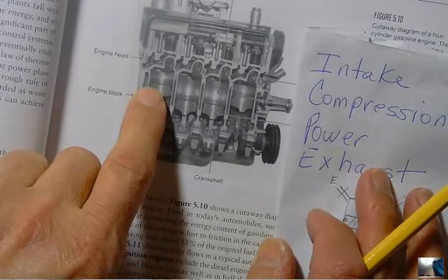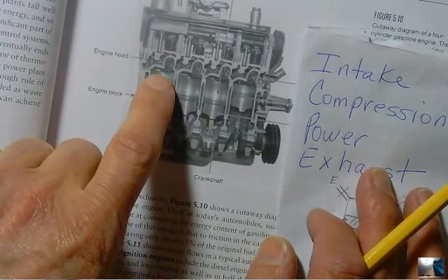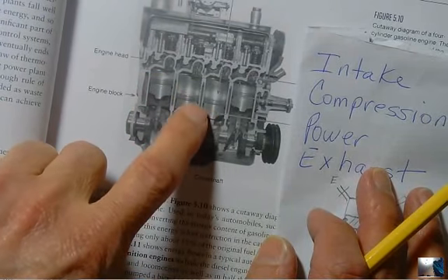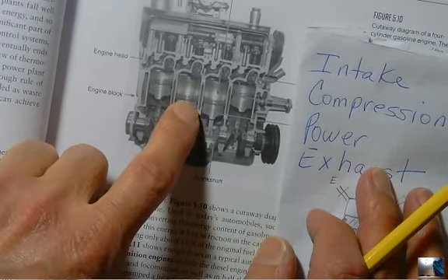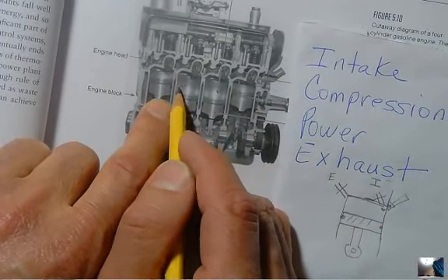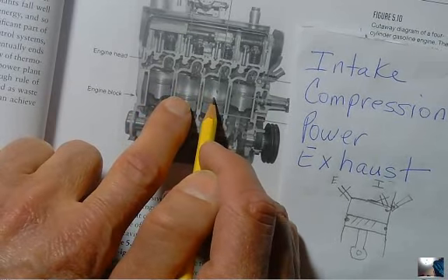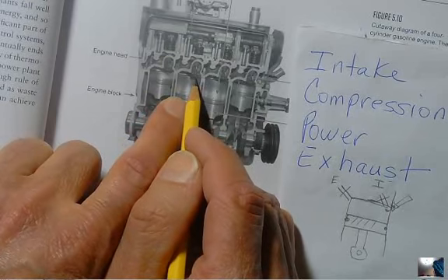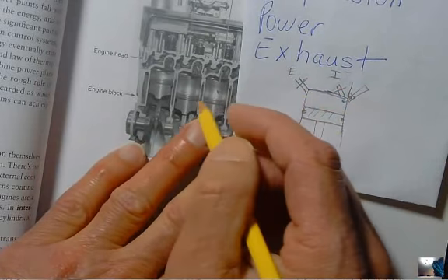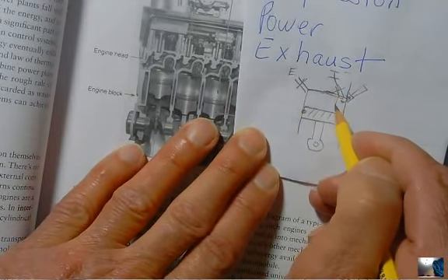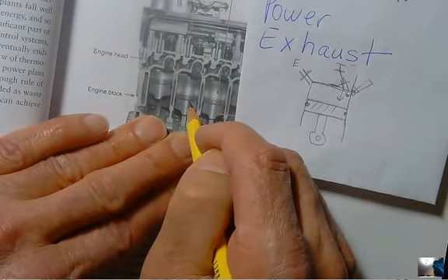If this cylinder number 1 over here is kind of up towards the top, let me start out with these 2 down ones. These 2 down here are just finishing up the intake stroke. What happens with the intake stroke is that when you get to the bottom here, an intake valve opens up, the exhaust valve closes up, and air gets rushed into this cylinder because it's under low pressure, because it just evacuated itself by pulling itself down to the bottom.